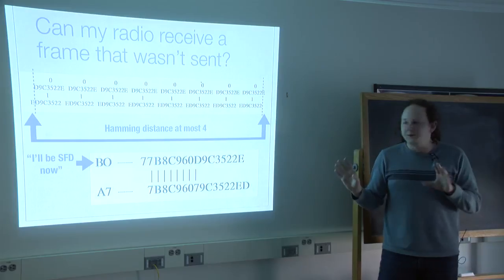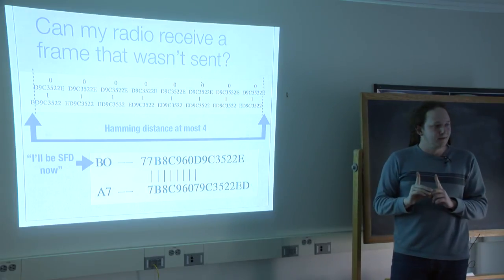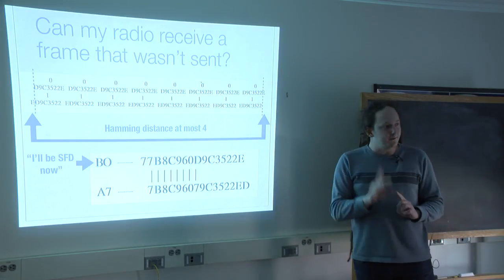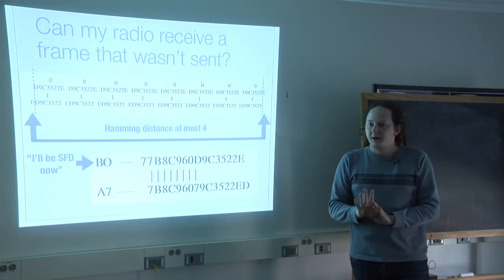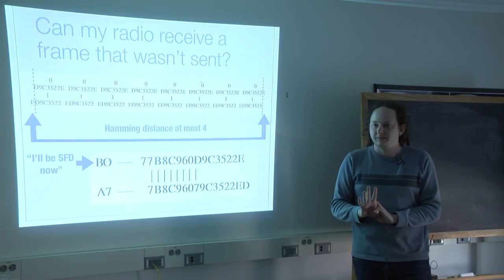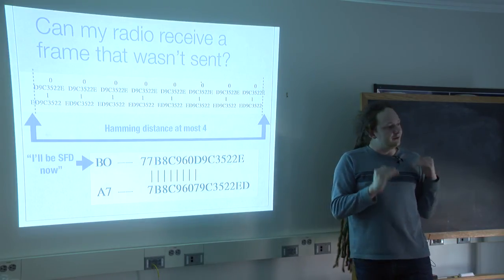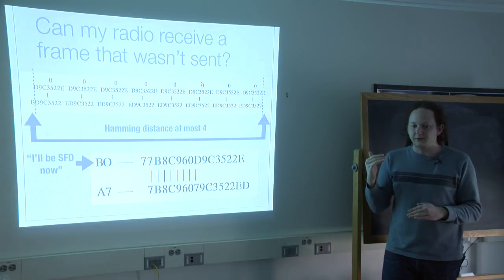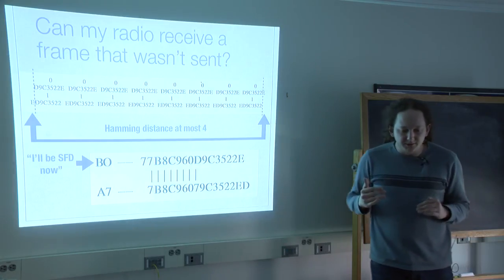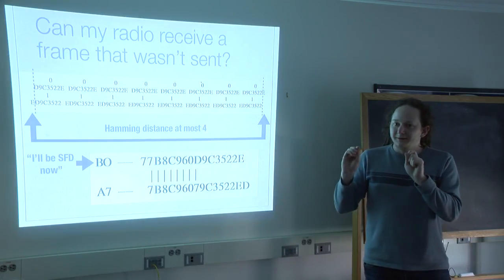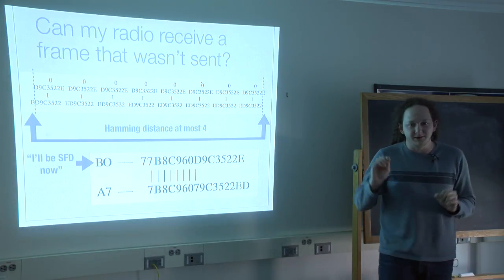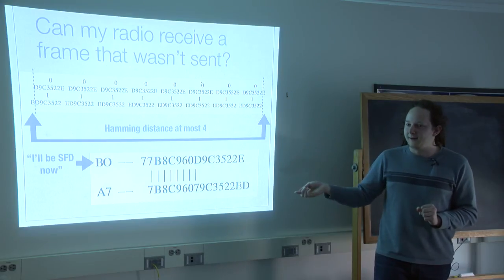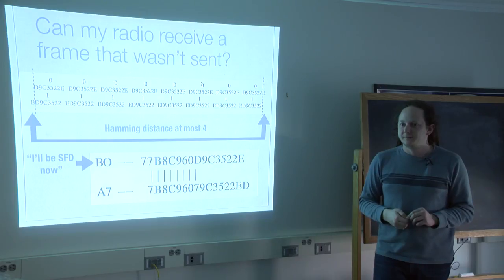For the entire sequence, everything but the tail end is correct. And that tail end, at worst case, if every bit is wrong, produces a Hamming distance of 4. And remember, the legitimate values have Hamming distances of like 13 to 16 between each other. So I can actually abuse the error correcting feature of this radio to let me smuggle through a packet-in-packet attack despite a defense that's trying to escape that sequence out.